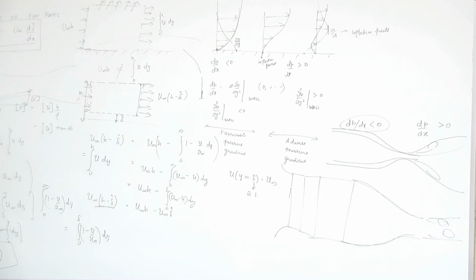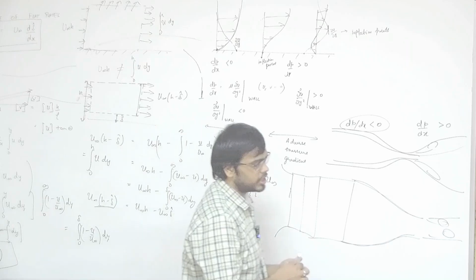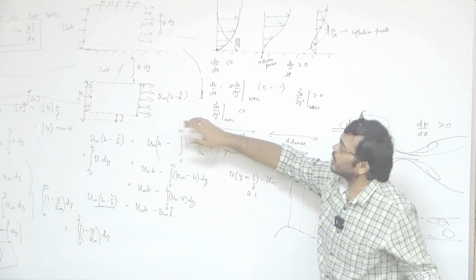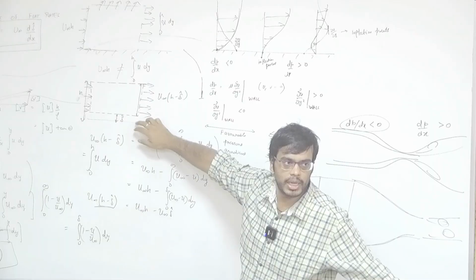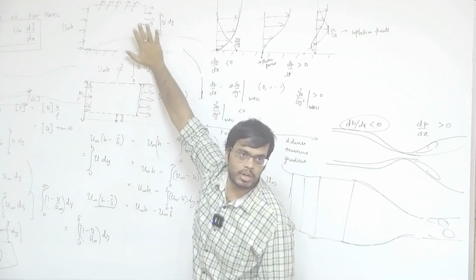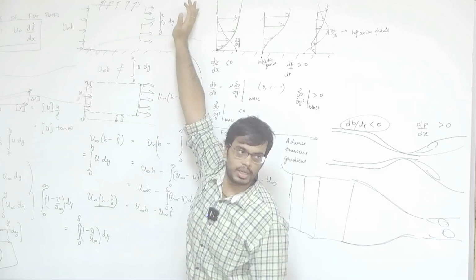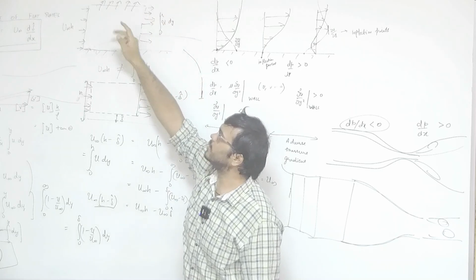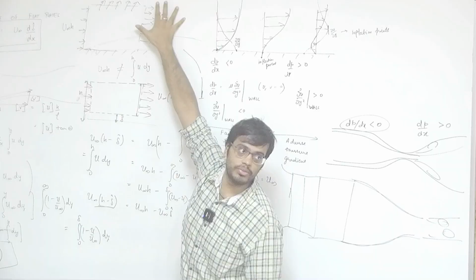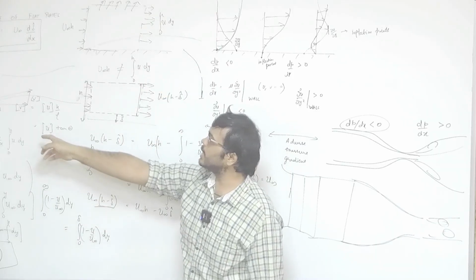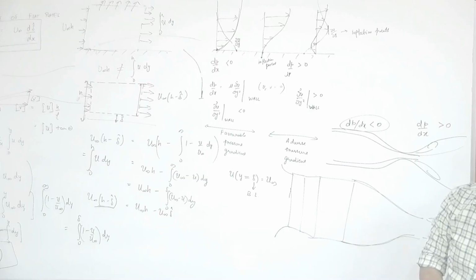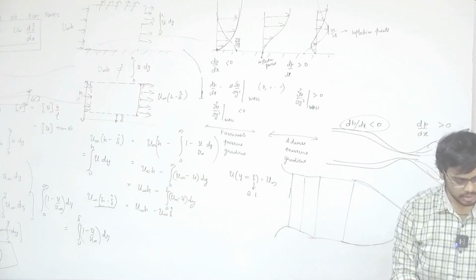The idea is that displacement thickness is trying to account for the presence of the boundary layer in changing the flow rate across this control volume of height h. If you have a control volume of height h, you have a flow rate coming out of this section. It is not equal to u infinity h, because there is a flow rate deficit. So, this is something less than u infinity h. How much less? It is actually less by u infinity times delta hat. You can do this calculation.